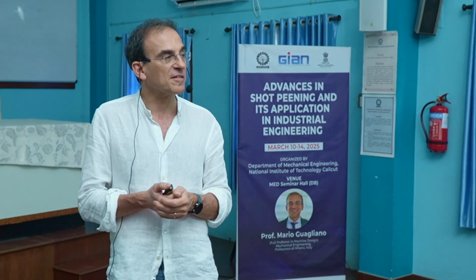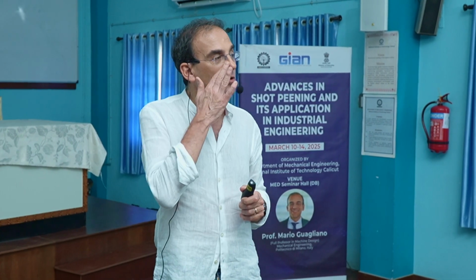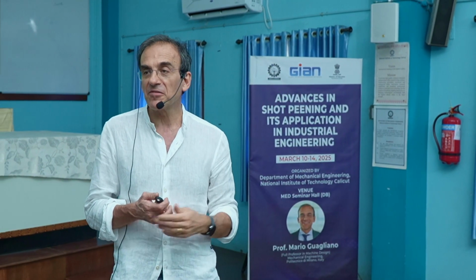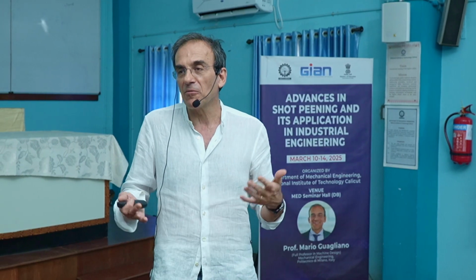The problem, what could be a problem? As was said, we have delta D over an initial D, D0, that is the theoretical one. What's happening if we do not know D0? Generally we can do this way: we use the first diffraction angle, psi equal to 0, perpendicular, instead of D0. Why can we do that?